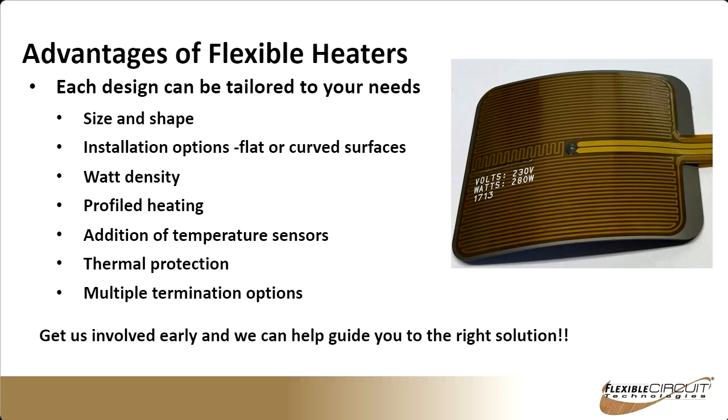They can be mounted on flat or curved surfaces, and they can be profiled. So within a single substrate, you may have one zone that you want to heat a little more for whatever reason, and we can adjust that heater pattern to allow for more heat or watt density in that certain region.